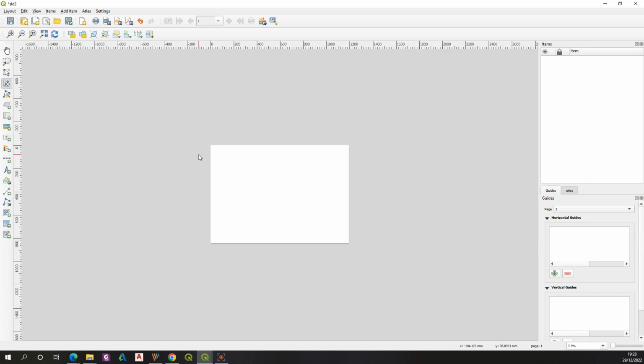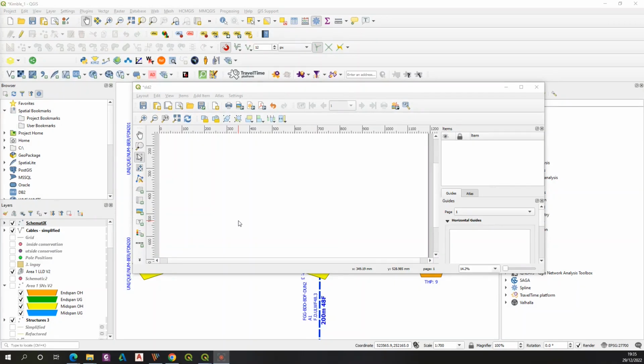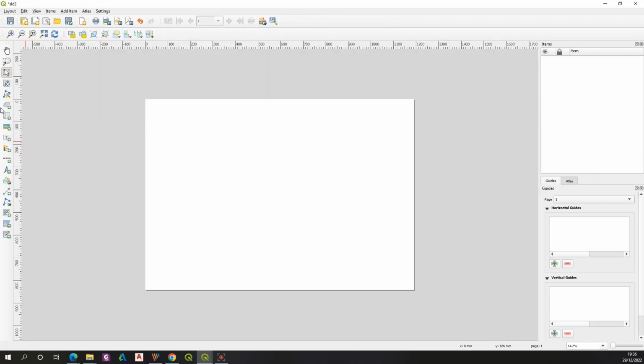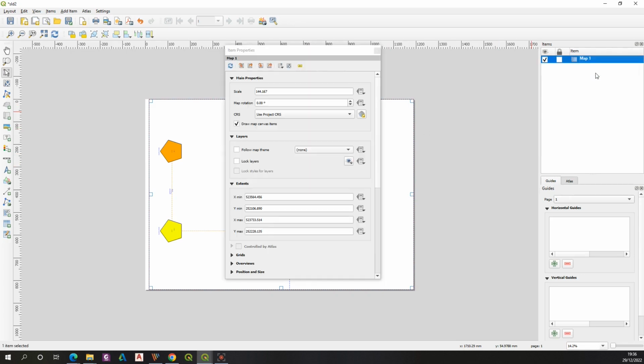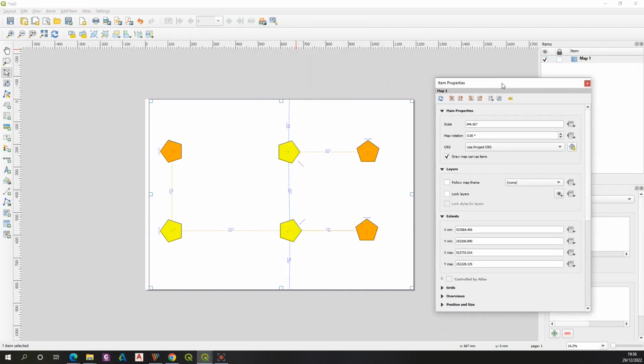It may take a while as our product is quite big, in order to show you how your job could look in this format. So make it slightly bigger and simply import the map. Rendering this way will give us nothing, because the scale already renders just the specified section of our project. We need to go to the item properties and change the scale accordingly. So the scale is not appropriate. Instead of 144, we need to place 700.